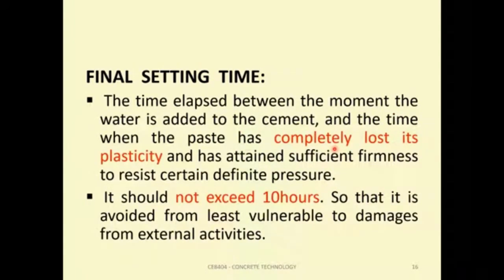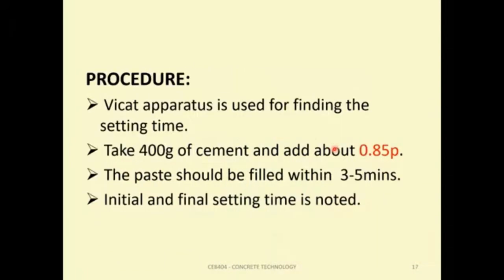The next one, final setting time. It is the time elapsed between the moment we add the water to the cement and the time when the paste completely loses its plasticity. That is, it attains a sufficient hardness to resist a certain definite pressure on it. It should not exceed 10 hours so that it can avoid damage from external activities.